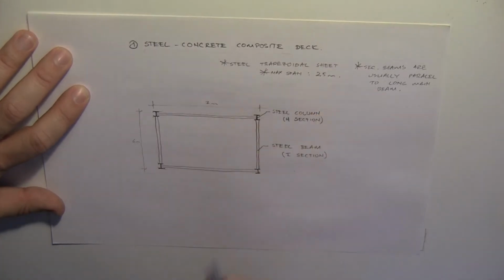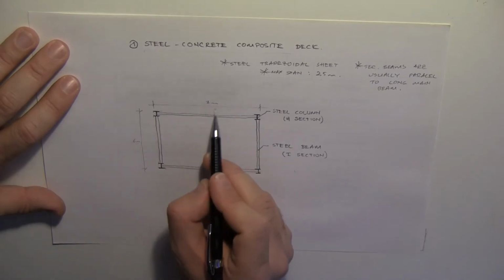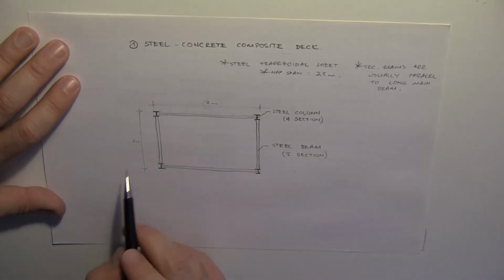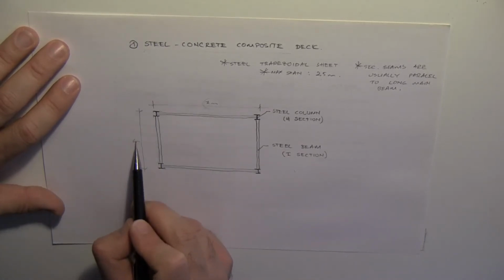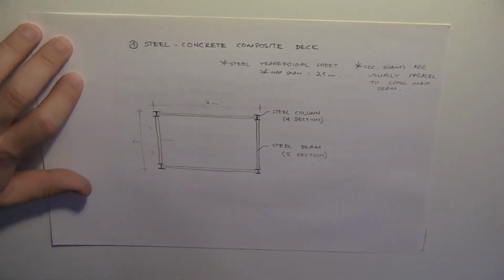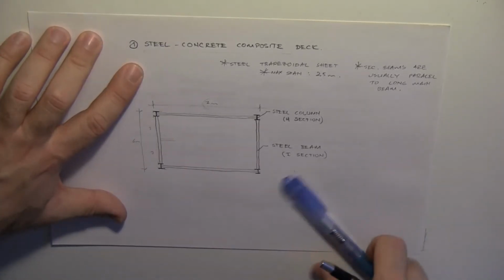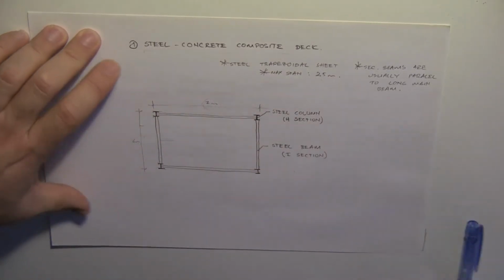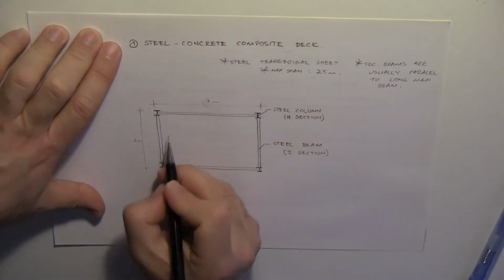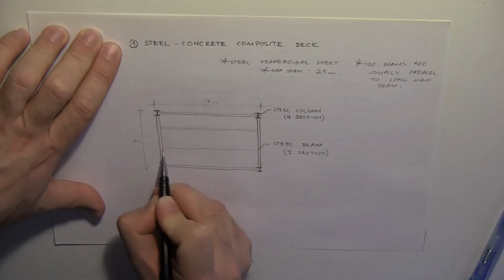Okay, and let's put asterisks here. And what we will do, maximum 2.5 meters. The long distance, large span is here, so the secondary beams will be in this direction. And in that direction, the span is 6 meters. If we just put a single secondary beam right in the middle, there will be 3 meters of span, which the steel trapezoidal sheet needs to pass. That is not possible. I need to reduce it to a span lower than 2.5 meters. That's why I need to add 2 secondary beams. Okay, so first secondary beam and the second secondary beam here.